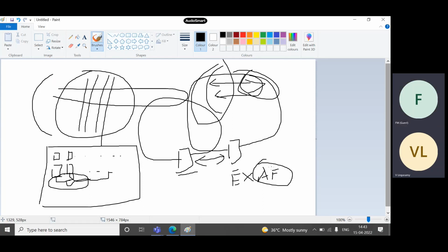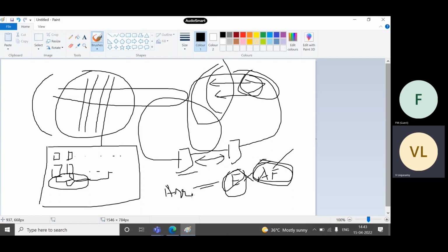Based on that, we can calculate the array factor. If you multiply the element pattern with the array factor, we need not multiply each and every element's radiation pattern together. We will simply multiply with the array factor and get the array radiation pattern. So here, constructive and destructive effects will happen.